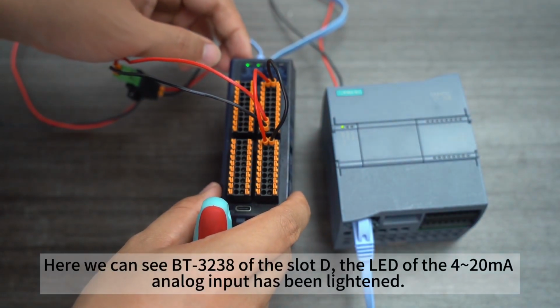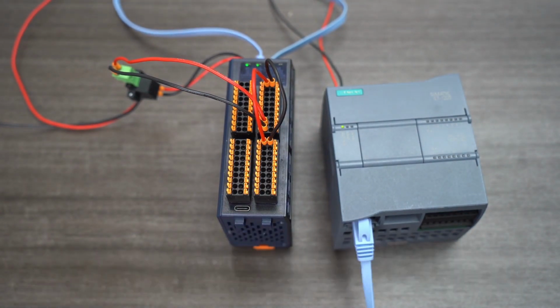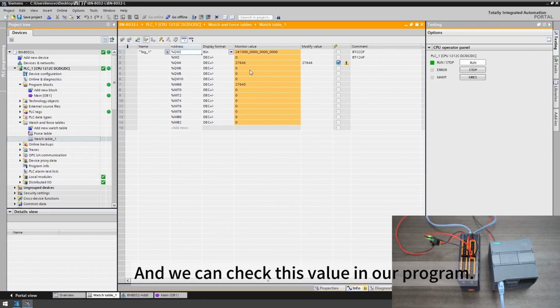Here we can see BT3-38 of slot D. The LED of the 4 to 20 mA analog input has been lit. And we can check this value in our program.